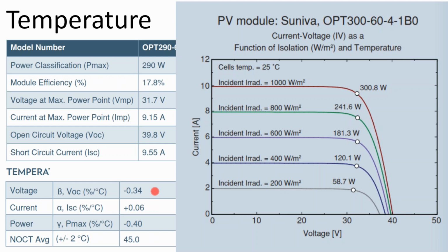Your peak voltage would occur on the coldest day of the year under full sun. And that can be problematic if you've put too many modules, solar panels, on a circuit. You could exceed the voltage requirements of the electronics they're connected to and then burn up or kind of pop the electronics. Current is more of a slow burn kind of thing. Voltage is more of an immediate explosion. You fry your microchips, they don't work anymore. You bricked your inverter rather than burned it.